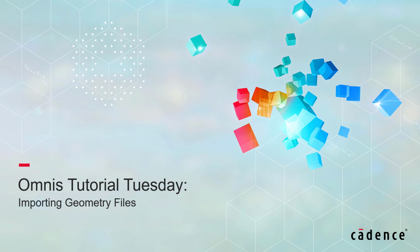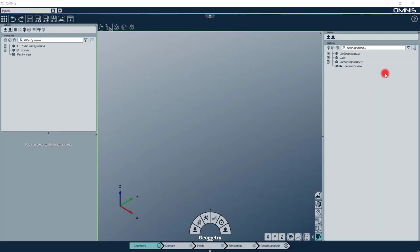in short videos of a few minutes. In this video, I will show you how to import a geometry file into Omnis. To import a new geometry into the CAD tree, use the down arrow above the tree. The up arrow is to export a geometry.